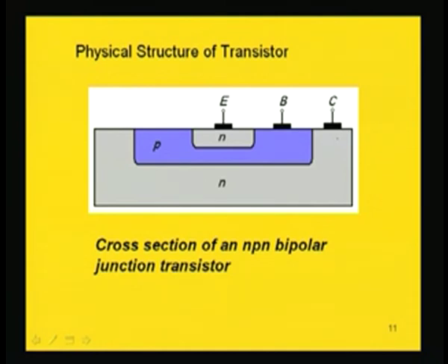So, IC will be very large, so the power dissipation capability of the collector should also be enhanced. That is why practically this area is made large, so that it can dissipate the power in a better way, because if the area is larger we can dissipate more without increasing the temperature. So, that is the reason why the collector region is the largest in a transistor. The base region is the least in cross section, and its width is also lesser.